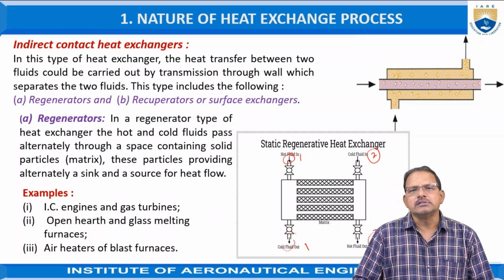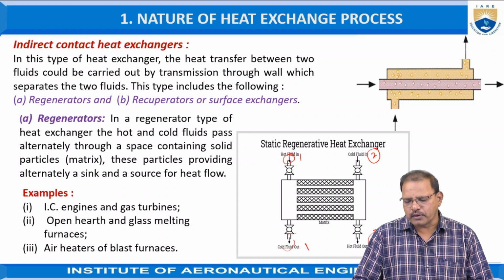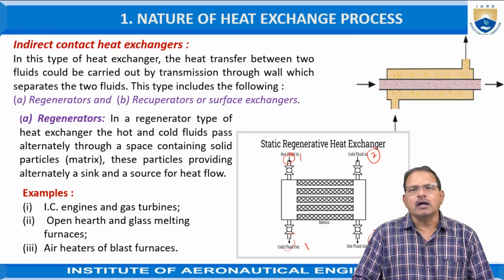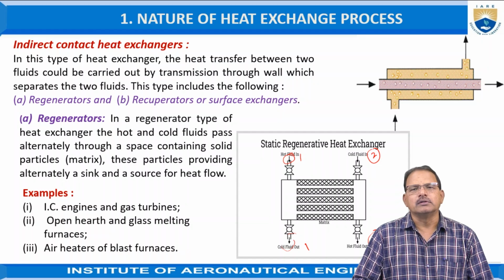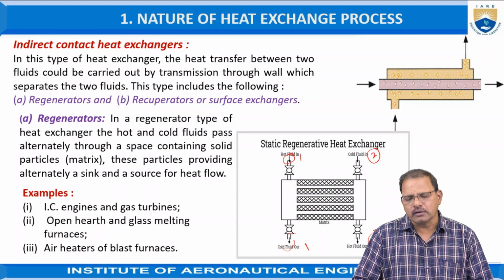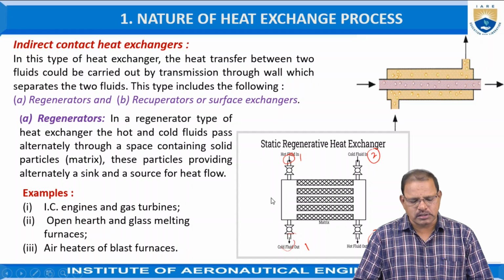This container also consists of a matrix of solid particles having high thermal conductivity. When the hot fluid enters the container with the solid matrix, the matrix extracts the heat energy from the hot fluid. Alternately, when the cold fluid enters the container, the heat energy held by the matrix, that is the solid particles, is given out to the cold fluid. So the heat is exchanged from the hot fluid to the cold fluid without any physical contact with each other.